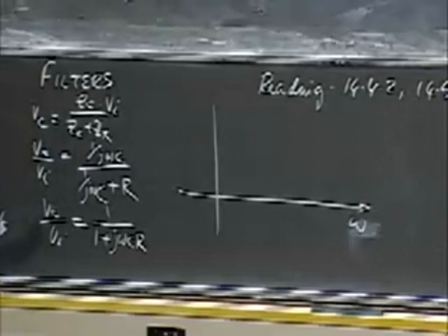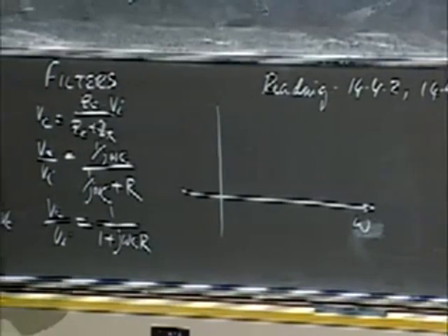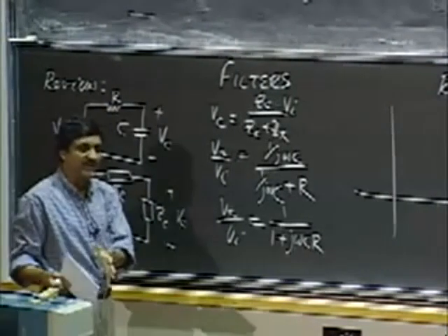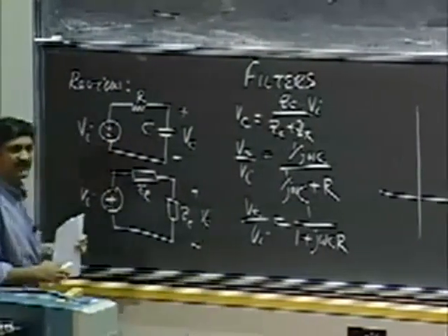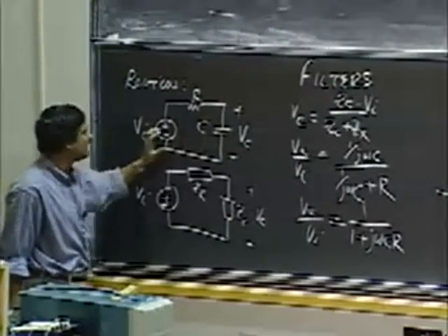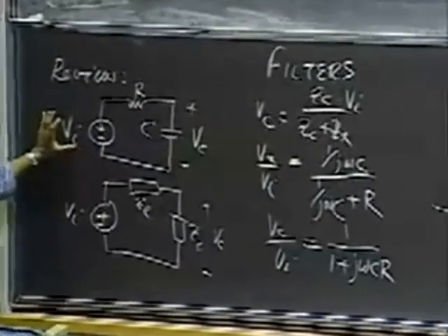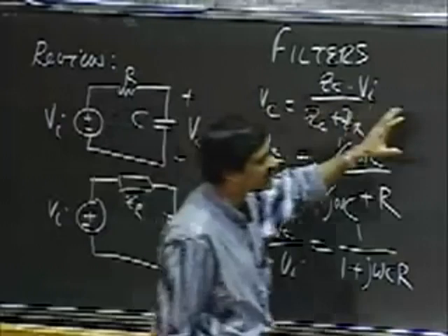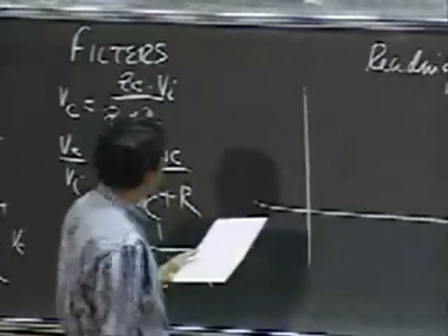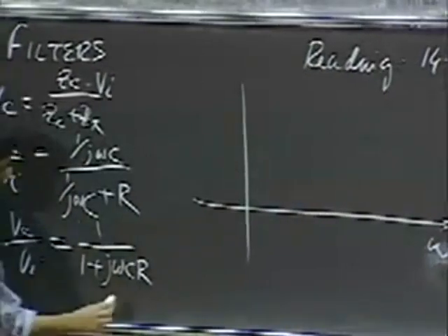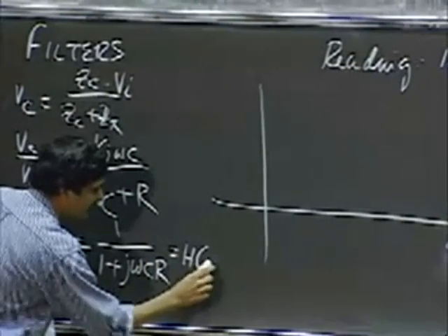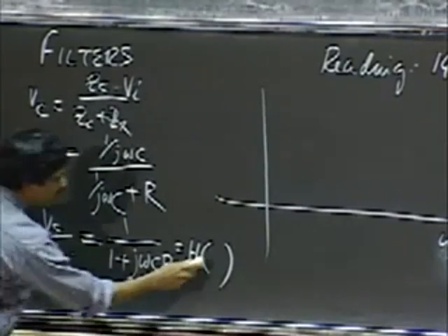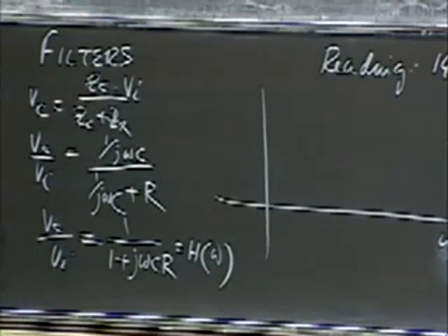So this represents a completely complementary view of circuits. The time domain view, and then there is a frequency domain view. The frequency domain view says, how does this circuit behave as I apply sinusoids of differing frequencies? Okay, so I can plot that relationship in a graph like this, and this relationship is simply given by a parameter H, the transfer function. It's a function of omega.